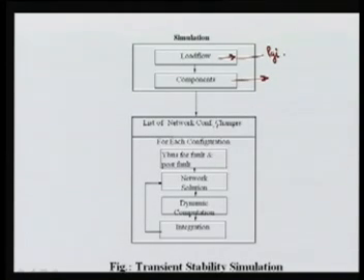Then you have to list the network configuration changes, meaning the pre-fault, fault and post-fault conditions, and for each configuration you have to form the Y bus. Then you have to solve the network solutions. Then you go for the dynamic solution of the whole dynamics of the system using integration techniques, and keep doing this until final convergence over the time domain where you are going to simulate.